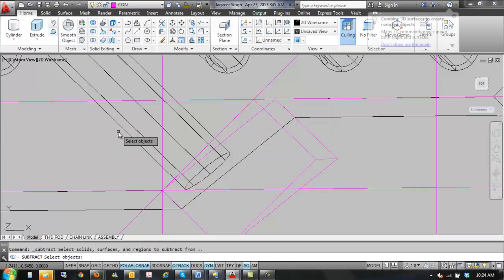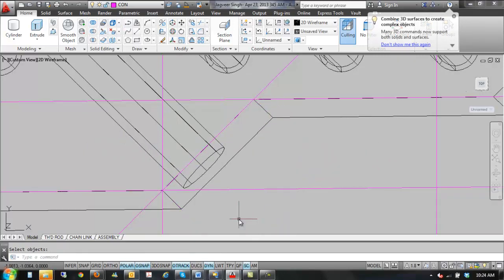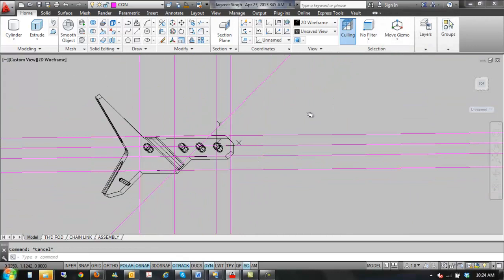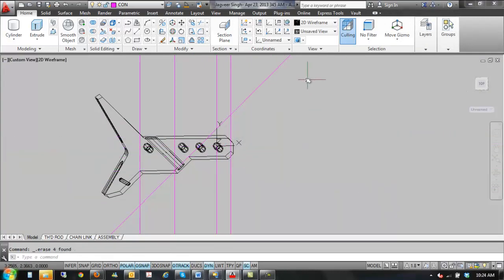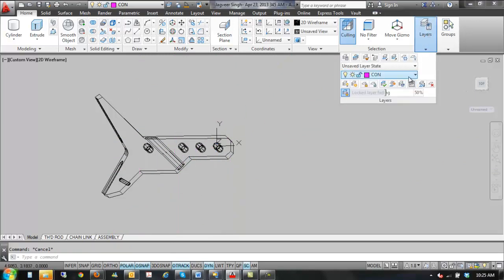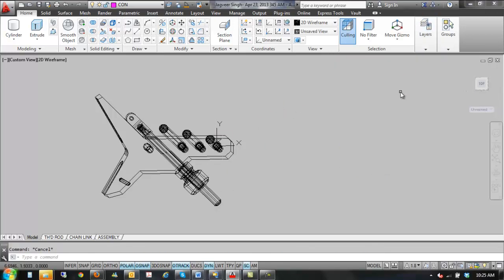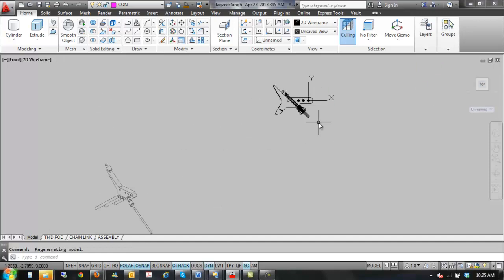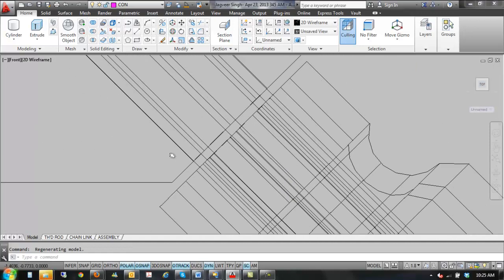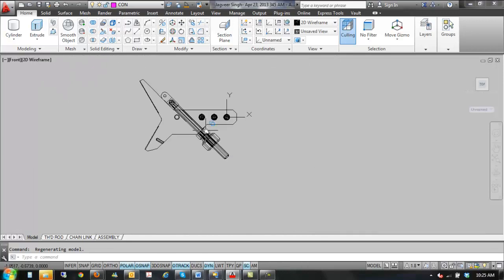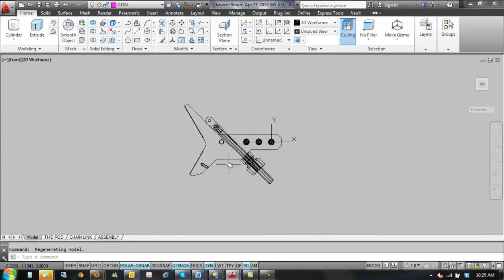And then go here. So subtracting from that object, you're subtracting that. And now your angle's okay, right? Delete all your construction lines. Now, you can turn on your layer, see everything again. And I think we should see something there okay. So click on top. Zoom in. Look at that, nice parallel space, right? So now you got everything there.